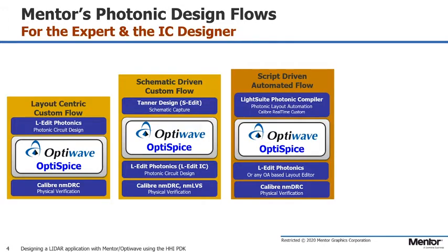We also provide a script-driven flow. This is with our LightSuite Photonic Compiler solution. This is for large-scale designs where you're dealing with a lot of optical components and a lot of electrical routing to control those optical components. This is done using Calibre real-time to verify all that execution in the script. Then finally, you do your final verification and layout in LEdit Photonics with both DRC and then driving OptiSPICE to verify your design.